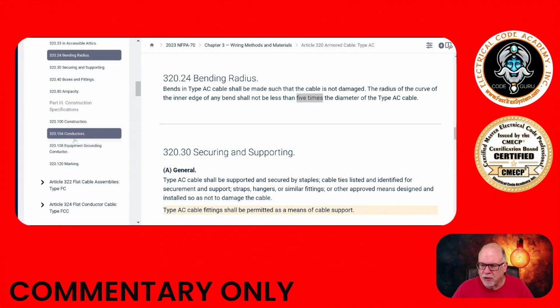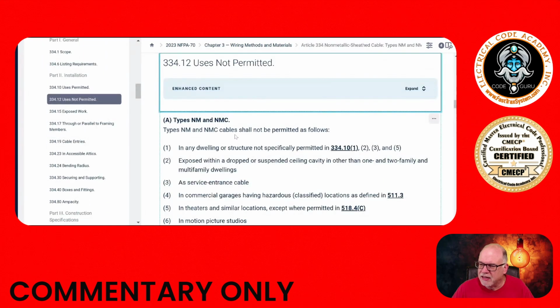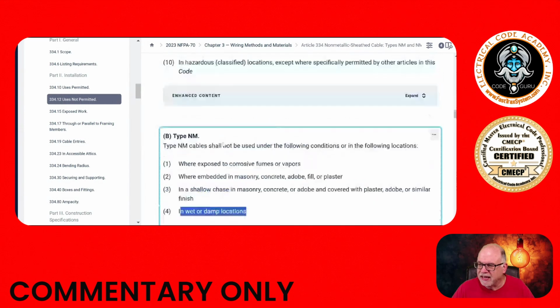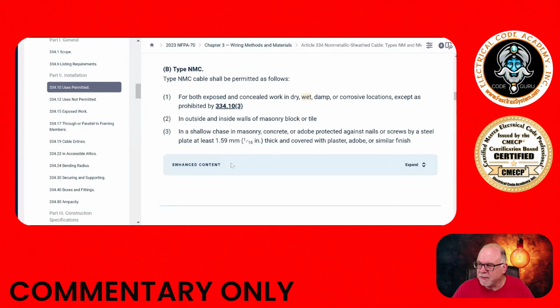Let's look at non-metallic really quickly. If you didn't already know this, you go down here to uses not permitted. We're talking about NM cable, so here's NM right here. And it says it's not permitted where? It's not permitted in wet and damp locations. Direct burial outside is a wet location. So boom, that eliminates that application, right? That's the first one.